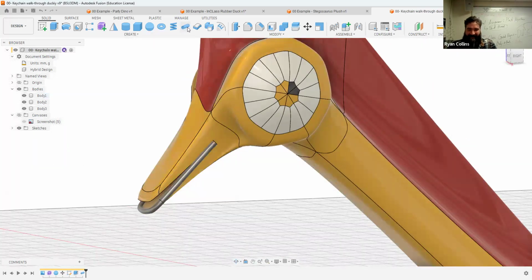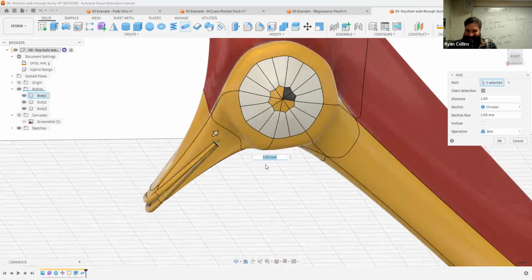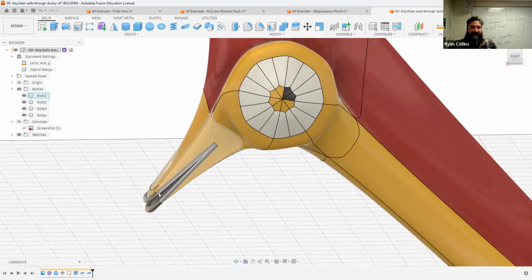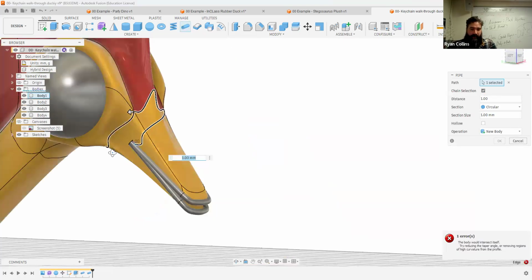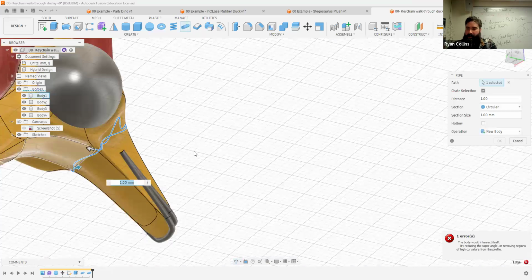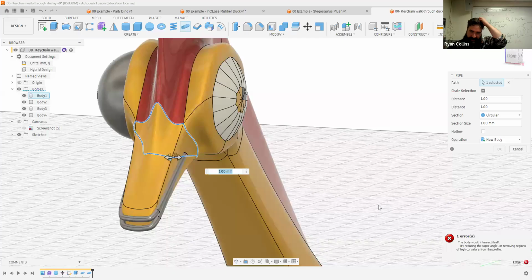So you can obviously do that to the top as well. Sometimes you can't do it all the way around. Sometimes making it so much worse. Sometimes the pipe tool will not follow along all the edge lines, but these edges, like say I could go around the edge here, that will work also. I'm being able to follow along where the quote beak would be. And let's create that as an edge. Now, see, it's giving me an error down here. It's self-intersecting, so I might not be able to do the whole thing. I can maybe do this as one piece.